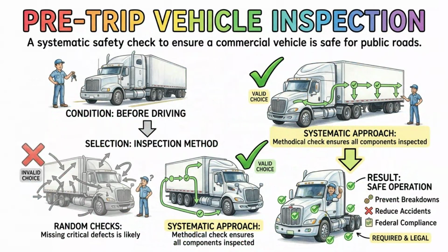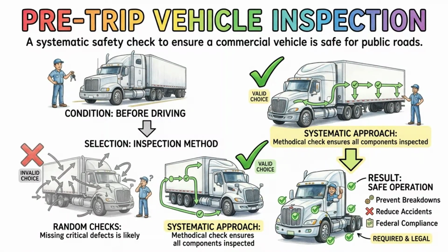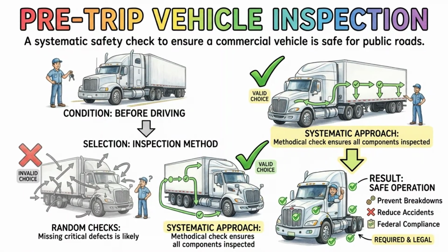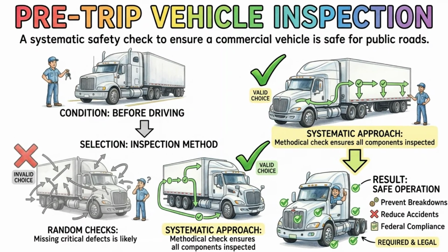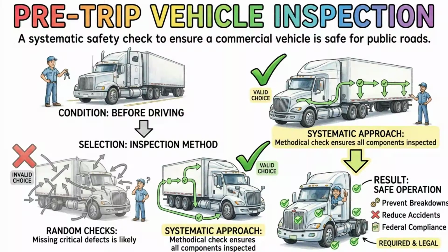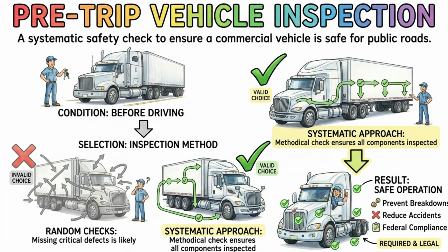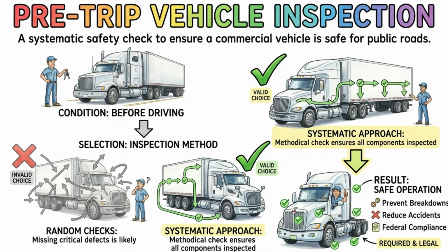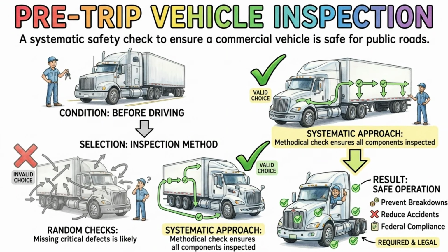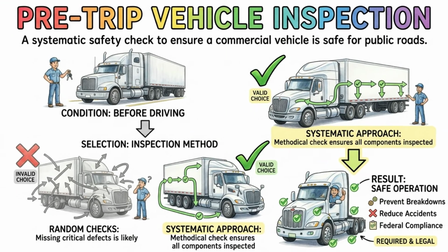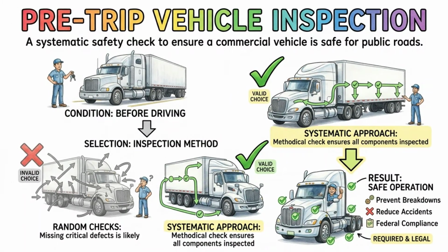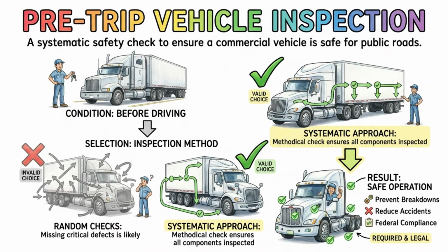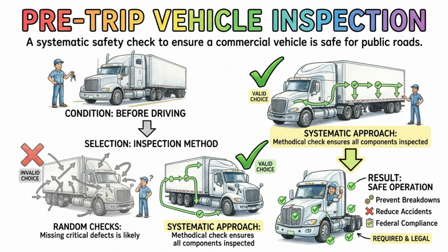Downshifting is a particularly important skill, especially before you start driving down a steep hill or entering a sharp curve. You must always downshift into the appropriate lower gear before you begin a descent, not while you are already going down the hill. This allows you to use the braking power of your engine to control your speed, rather than relying only on your service brakes. If you ride your brakes down a mountain, they will overheat, fade, and eventually fail completely. The exam will heavily test your understanding of using engine braking instead of service brakes on downgrades.